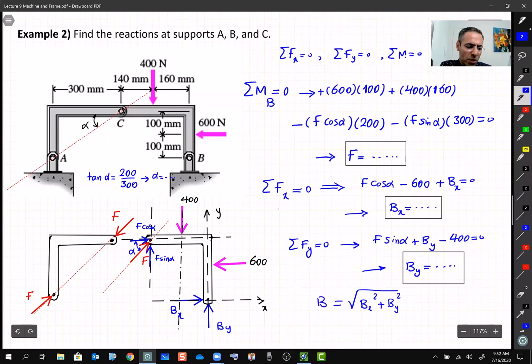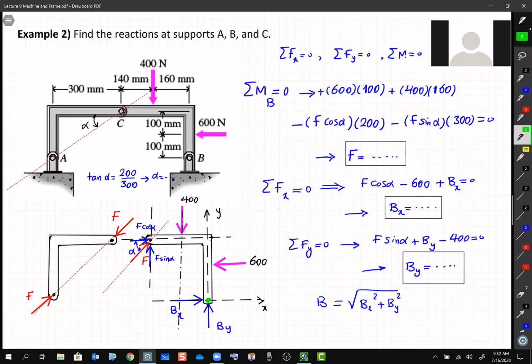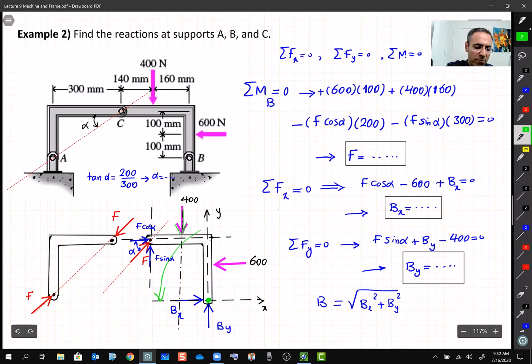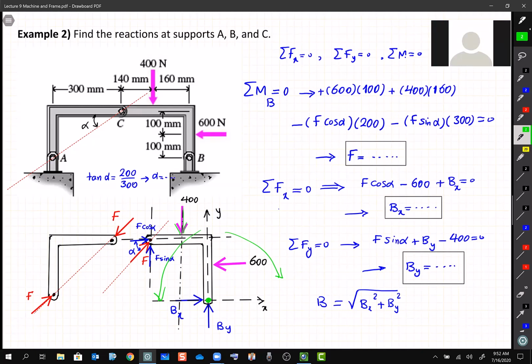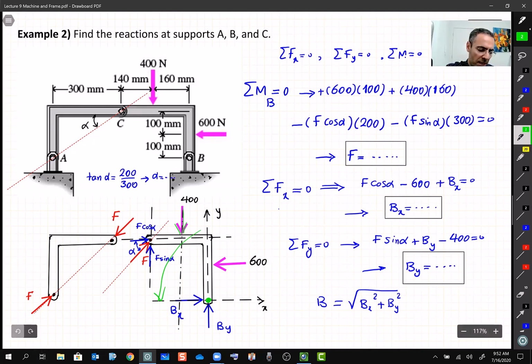All right. So let's try this one. In the image below, if we say that things can rotate around point B, right? If you put a weight of 400 here, this weight is gonna fall these things to the left or to the right? It would be to the left. Yeah. To the left, right? If it is to the left, then how is it rotating? Then it's rotating counterclockwise. Yeah. Counterclockwise, right? Yeah, it's positive. So always try to visualize it, and maybe try to exaggerate. Then probably it's easier to follow. Okay.